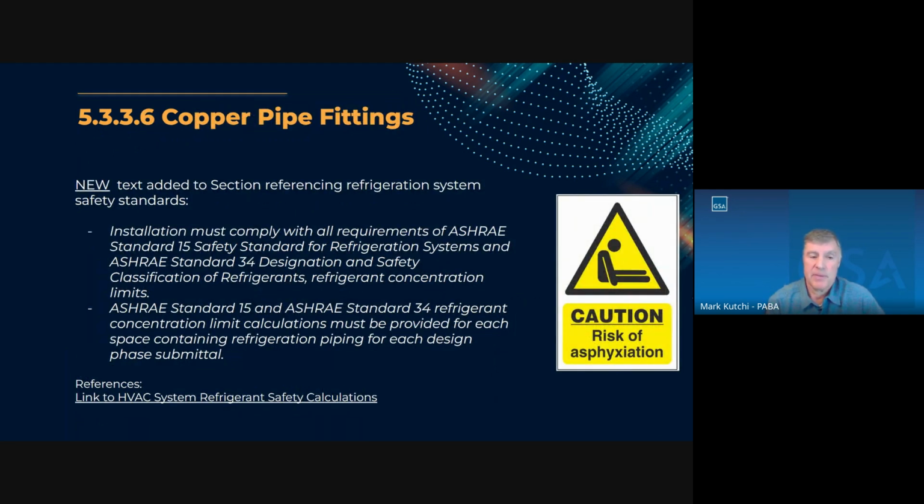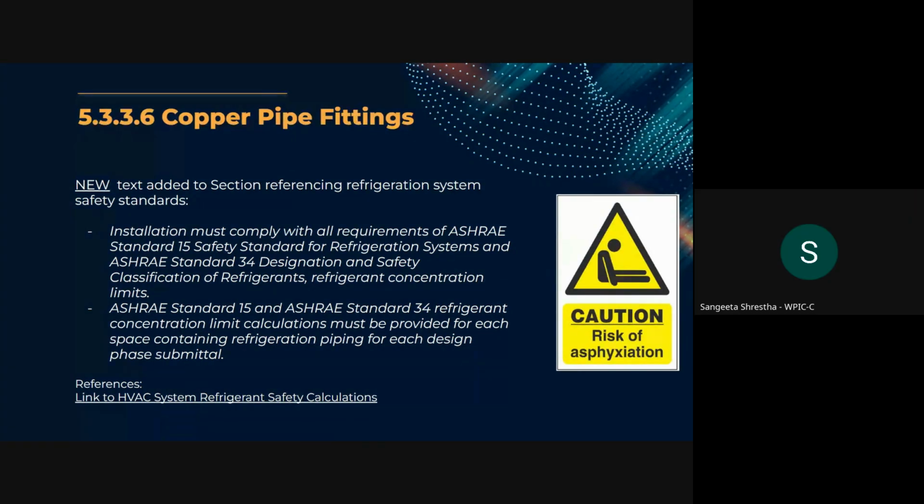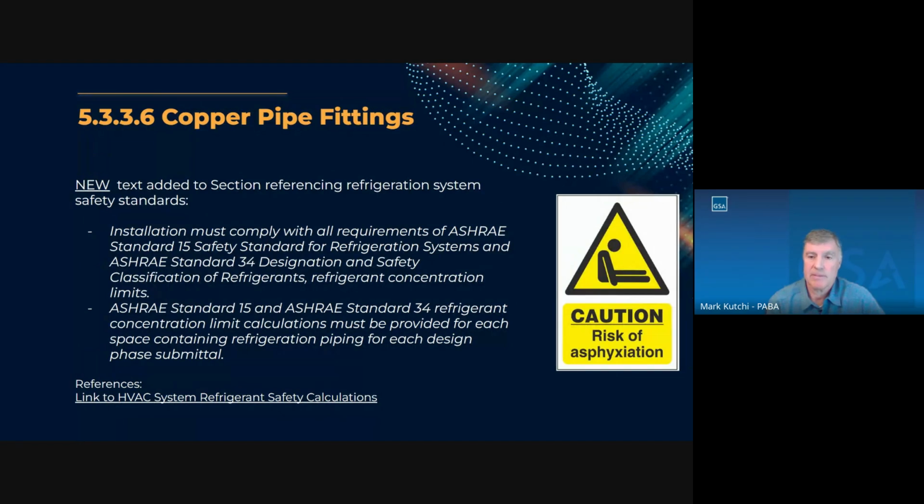In the copper pipe fitting section of the chapter, new text was added referencing the refrigeration system safety standards: ASHRAE Standard 15, safety standard for refrigeration systems, and ASHRAE Standard 34, designation and safety classification of refrigerants. Those are the two standards that define the refrigeration ventilation that must be provided to rooms.